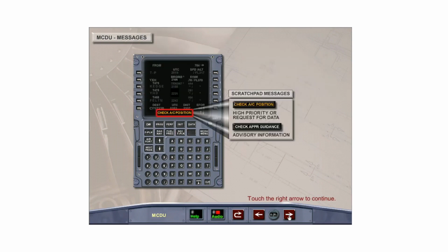The MCDU scratchpad will also display specific messages generated by the FMGC. Higher priority messages are displayed in amber and cover navigation messages, data entry errors, and Nav Display repeat messages. White messages are advisory only. Messages can be cleared using the Clear key. A list of all MCDU messages is contained in the FMGS Pilot's Guide, Volume 4, Chapter 3, MCDU Messages.